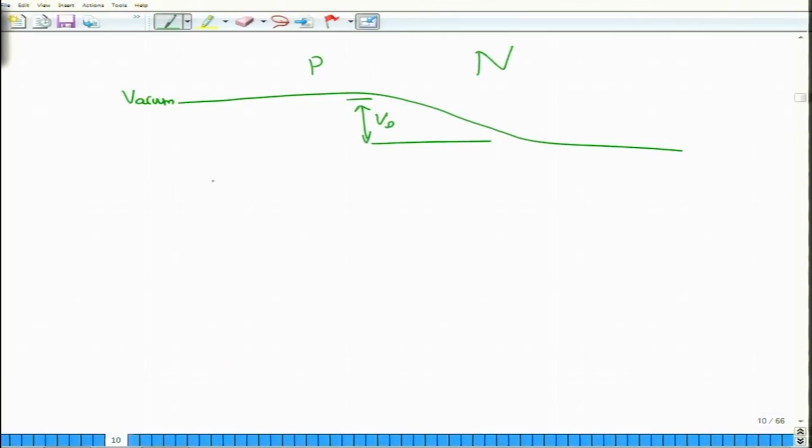However, that is not the case for the conduction band, because in the conduction band case, what happens is initially it will go like this. If it was a small n, it would have continued and dropped, right, but this is not a small n, this is a capital N. So, it can't continue forever, but it does go down and then goes back up. It will never reach a level beyond here. So, it goes back up here and then goes down and then becomes EC2 on the other side of the